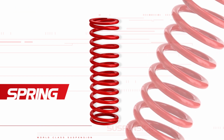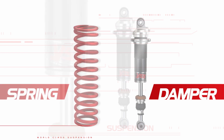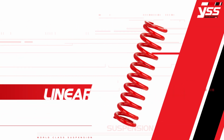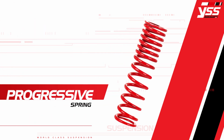Spring supports the weight of the bike and rider. Damper is to control and balance the spring's vibration and movement. Most vehicles typically use coil springs, which have two types. 1. Linear spring has consistent coil spacing and builds up resisting force linearly. 2. Progressive spring has variable coil spacing.